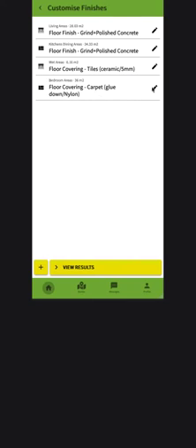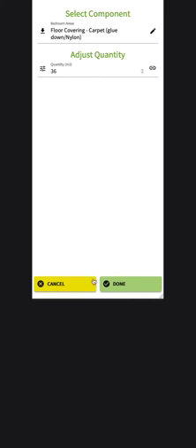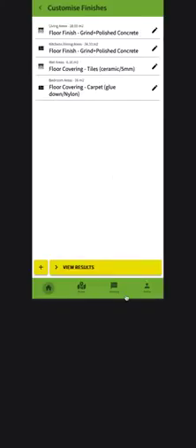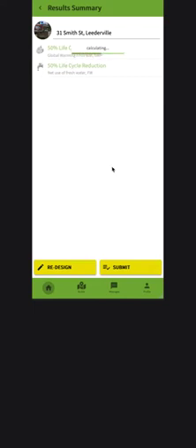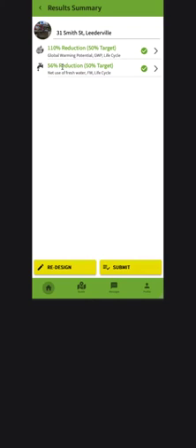I'll leave the carpet in there and just see if that comes up as one of the bigger remaining impacts. So we'll see where we ended up with our targets. So that's great. We actually ended up with a net zero carbon, a bit better than net zero carbon global warming potential. I'd say a lot of that is due to that PV system, particularly because it's only a 3-bedroom home, so not a lot of occupants, so large PV system for not a lot of energy demand. But we did change a lot throughout that very quick assessment, and it's pretty cool.